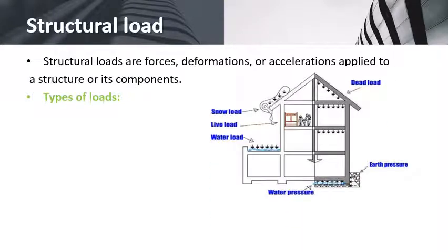Gravity loads. Firstly, I will talk about dead loads. Dead loads are relatively constant over time, also known as permanent or static loads. Secondly, live loads: dynamic or moving loads, temporary and of short duration, considering impact, momentum, vibration, and dynamics of fluid.